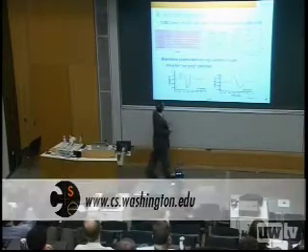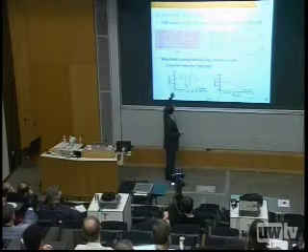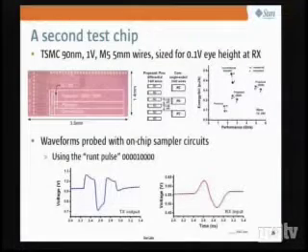In a 90 nanometer technology, 1 volt, we looked at conventional repeated wires and compared them with this notion of the return to zero signaling, either single data rate or this dual data rate system. We try to do it fairly. So in the middle here, you can see that for the conventional repeated wires, we gave twice the pitch, twice the width, twice the spacing to give it sort of the same footprint.